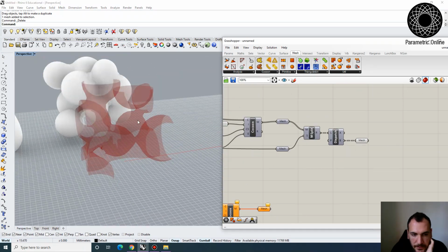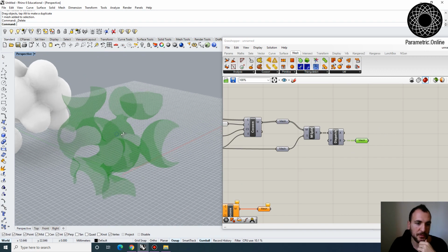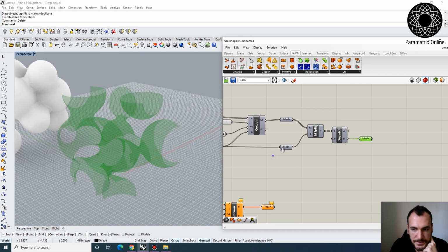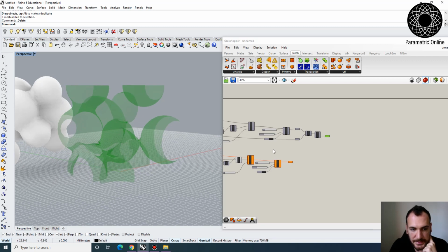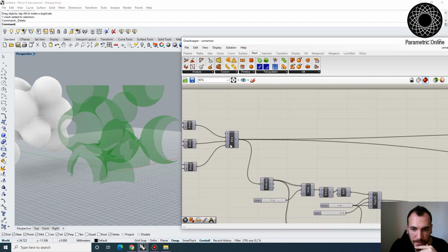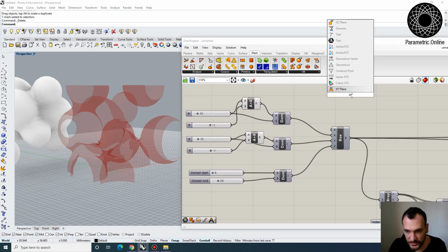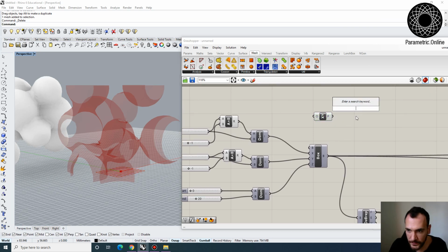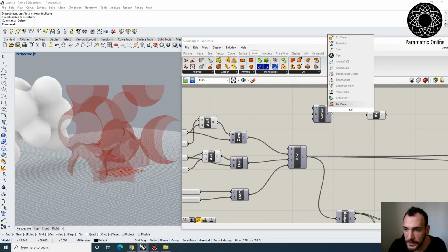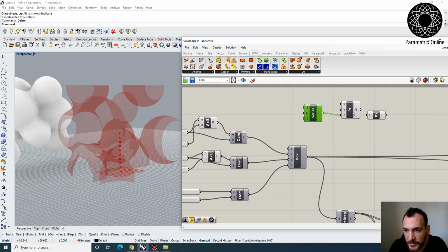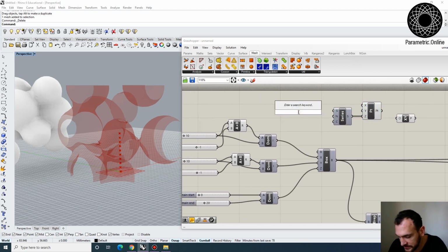I want to first show you the workflow, which is we split the mesh so that we get the inner hollow parts. Then what I want to do is get the floor slabs placed and split the floor slabs with this mesh. So to do that, we go back to the box, the dimensions for the box. So I want to create a series of planes in the vertical direction. Those planes are going to be XY planes. And I want to create a series here. So the series are going to be connected to a point, XYZ point. So these are going to be the Z values. And we can define some sort of interval. Let's say we want floors that are on every fourth level.